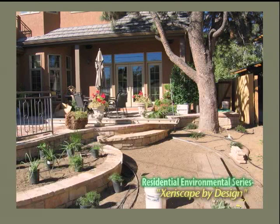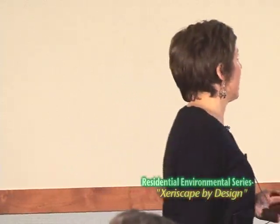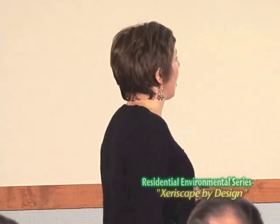So we designed where these walls went, and then the veneer on them is a stone veneer. It's a little bit hard to see in the slide, but that's a very thin stone. It's applied like brick to the wall to make it look like a natural stone wall. But these walls were super structural, so a natural stone wall wouldn't have been appropriate. Most of the time we build our stone walls as gravity walls, because it's less expensive and it's more sustainable. But here we had to use a veneer product.